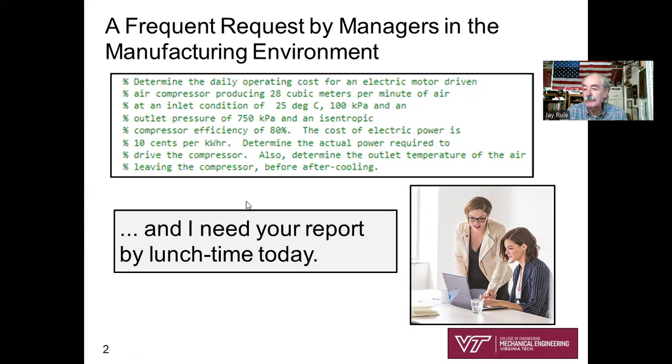Here's the request from a manager: Determine the daily operating cost for an electric motor-driven air compressor producing 28 cubic meters per minute of air at the inlet, with inlet conditions 25 degrees C and 100 kPa, very much an atmospheric situation, an outlet pressure of 750 kPa, and an isentropic compressor efficiency of 80%. The cost of electric power is 10 cents per kilowatt hour.